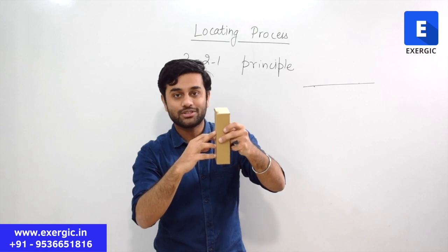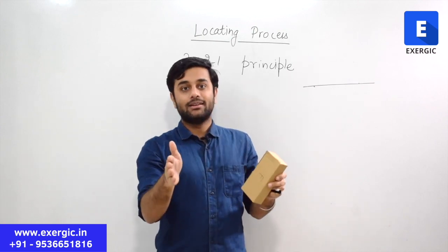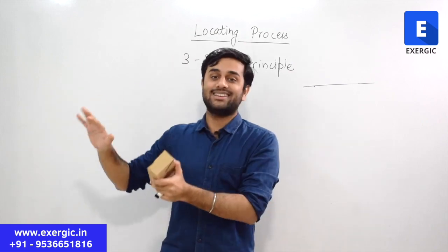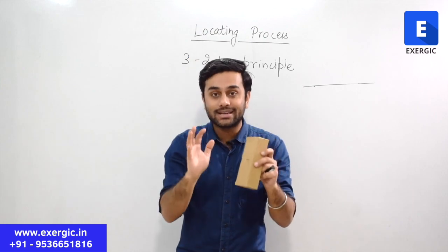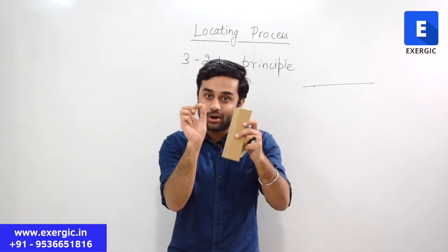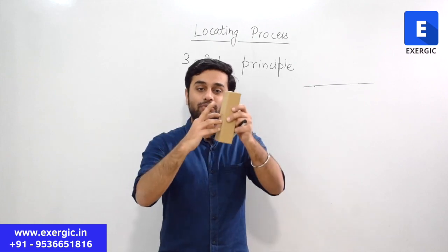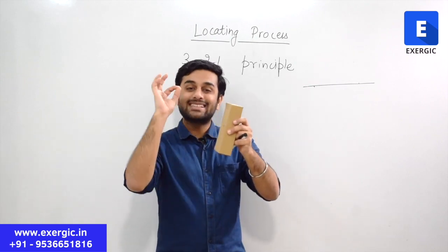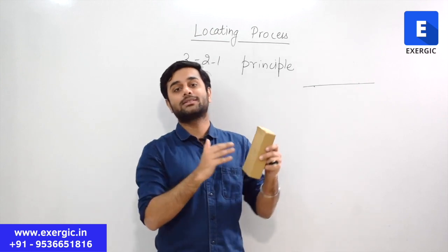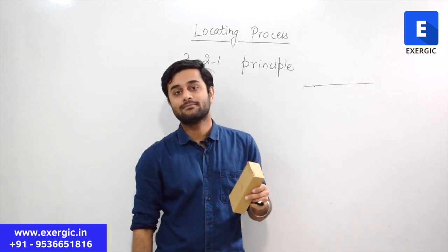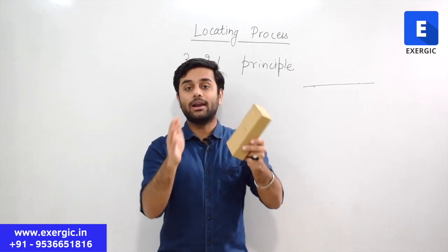Hence, it is not possible to have all 4 points exactly in any plane, manufacturing wise. Theoretically, you can, but manufacturing wise, there will be some tolerances, so you can never ensure that the fourth point will exactly lie on this plane, which is defined by the first 3 points. It is impossible. What will happen as a result of that? There will be certain wobble.